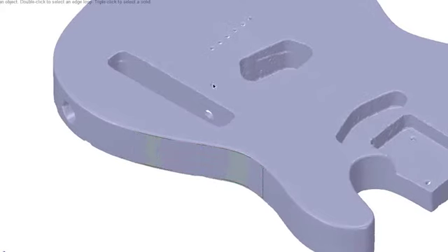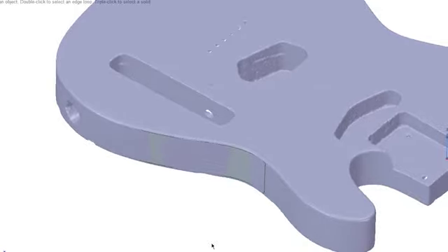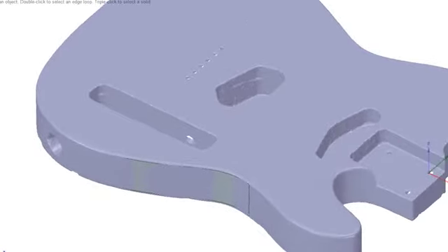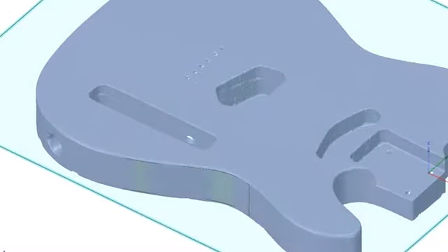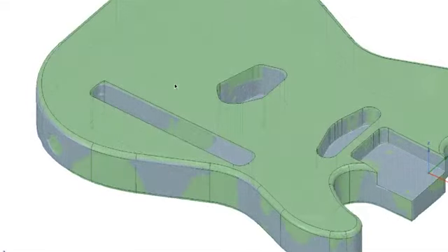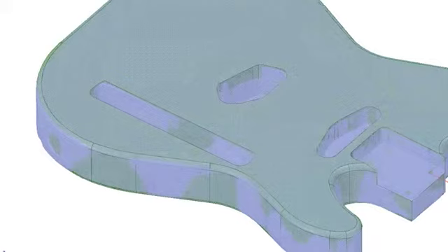Okay. Another one that's come in is, is there a way to see how accurately the extrude fits to the scan data, perhaps a color deviation plot? Yes, we do have the color deviation. Inside, I have the deviation tool right here. That's another excellent question. I can say that I want to select a mesh body and a solid body and do a color deviation between the two. Okay.